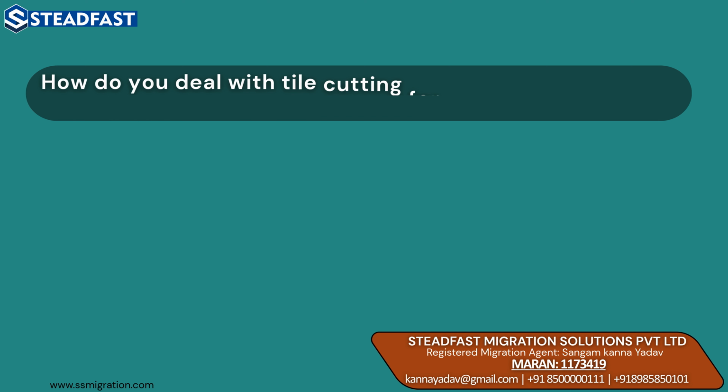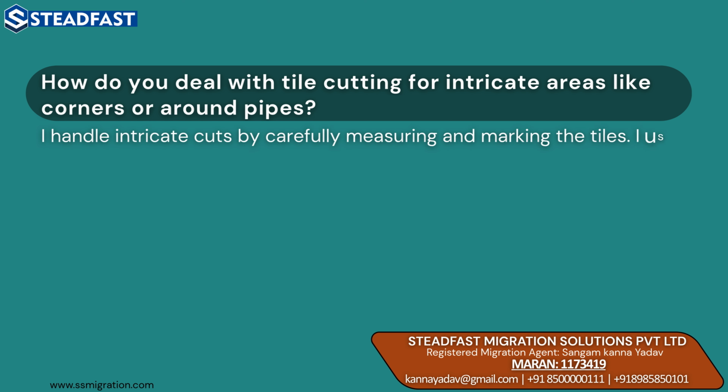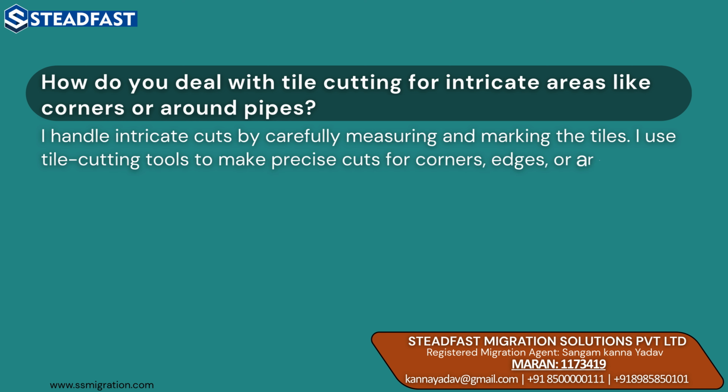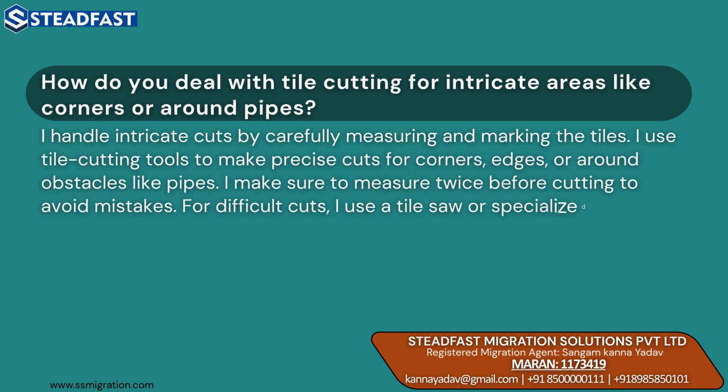How do you deal with tile cutting for intricate areas like corners or around pipes? I handle intricate cuts by carefully measuring and marking the tiles. I use tile cutting tools to make precise cuts for corners, edges, or around obstacles like pipes. I make sure to measure twice before cutting to avoid mistakes. For difficult cuts, I use a tile saw or specialized tools to ensure a clean and accurate result.